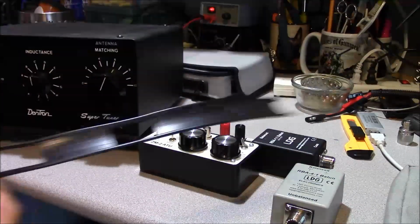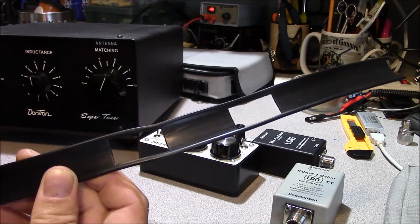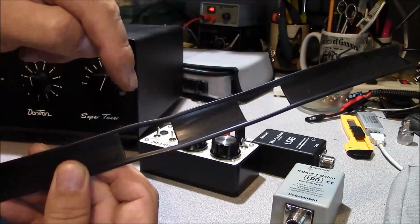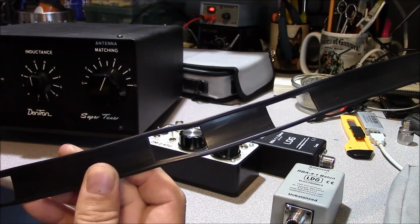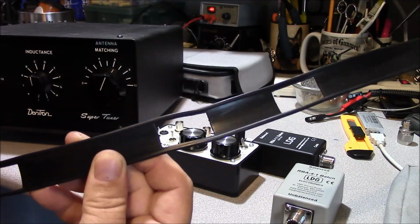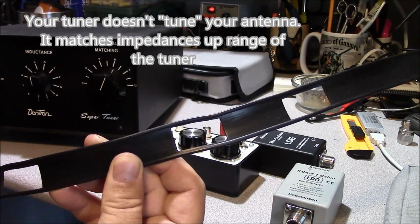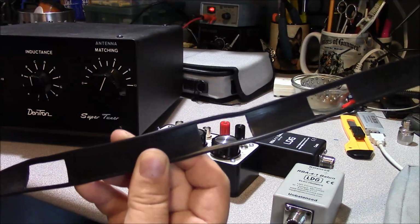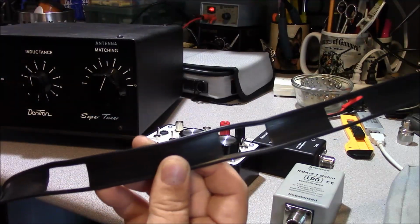Window line such as this is very popular in amateur radio. It makes for very effective multi-band antennas because there's much less loss in parallel feeder than there is in coaxial cable under high SWR conditions. So in the instance of making a multi-band dipole or any kind of multi-band antenna, having it fed with a balanced feeder provides for a more effective solution than feeding it with coaxial cable.